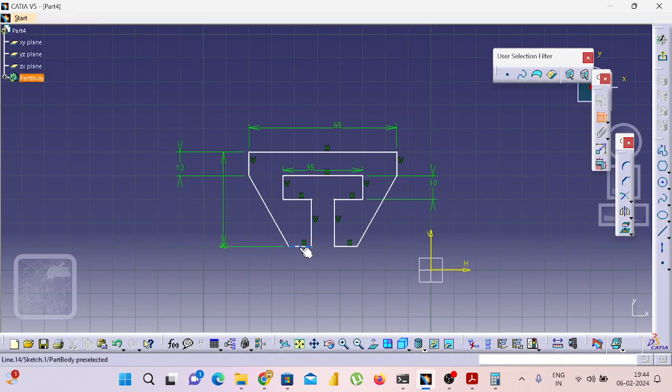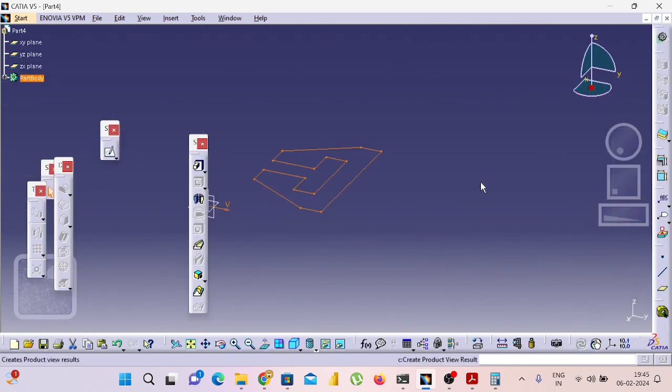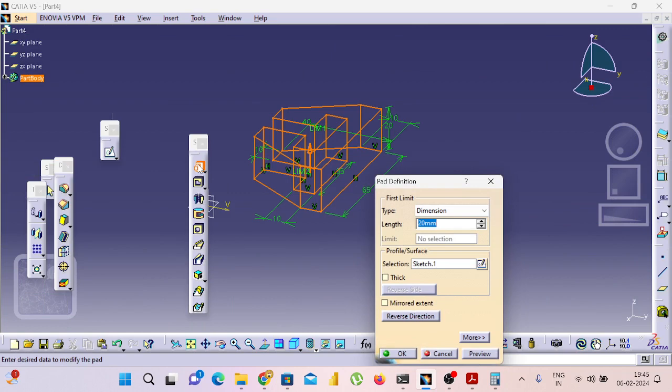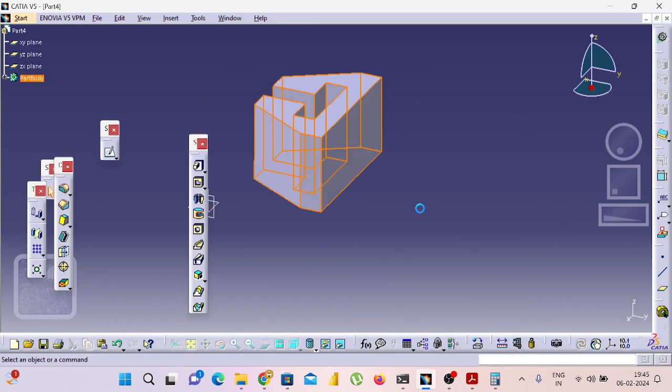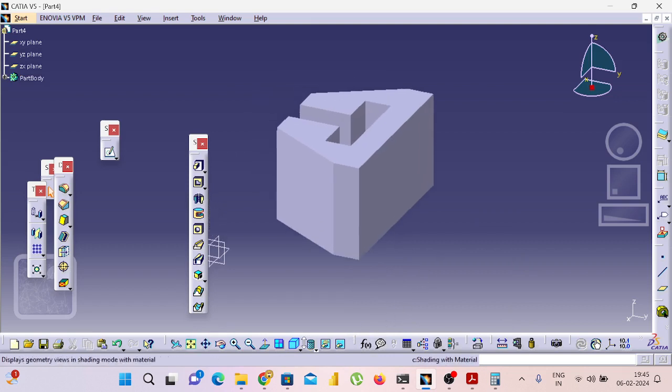If you want, we need to give this distance. Right, like this we can give the dimensions. We can do the extrude also easily. We can do the padding also. Right, directly enter the pad, enter the angle like 35, enter. Right, fit to screen. Right, isometric view.